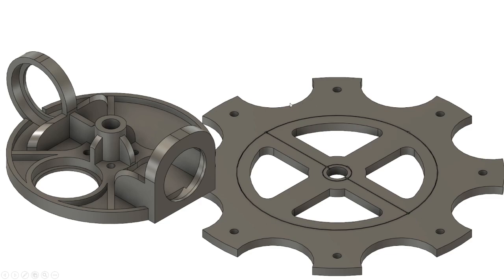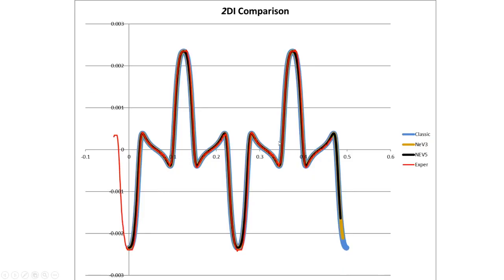If I called it an armature, I mean it's a stator, and we can swap this out for each one of the different experiments, and then we just move the magnet from slot to slot to take all the different magnet configuration measurements. Now you'll notice we have a little areas where things don't fit. That's because we have about 45 microvolts of ripple, and we'll get into the ripple in a few moments.